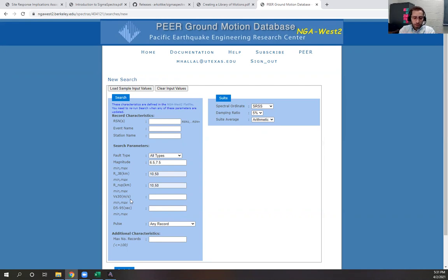So the bedrock at the site is consistent with this design response spectrum. And that is where you will be inputting your ground motions. So we will input the ground motions at the bedrock level and then propagate them through the soil to perform 1D analyses. So you want to select ground motions that are consistent with these conditions, that are consistent with the design response spectrum, that are consistent with where you are inputting your ground motions.